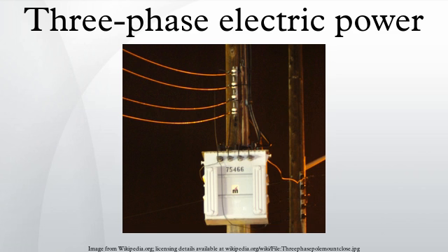Three-phase loads. An important class of three-phase load is the electric motor. A three-phase induction motor has a simple design, inherently high starting torque and high efficiency. Such motors are applied in industry for many applications. A three-phase motor is more compact and less costly than a single-phase motor of the same voltage class and rating, and single-phase AC motors above 10 horsepower are uncommon.